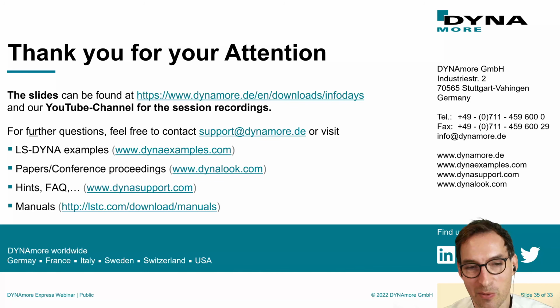Okay, just as a follow-up question, last one. I think this applies to ALE and SPH, right? The question is, does it work with all material models? No. With ALE, you have this advection step all the time, and advection requires a special treatment also in the material. A lot of materials are implemented, the usual suspects, I would say. Give it a try. LS-DYNA will tell you, hopefully, that this material is not supported. Run a really simple example with the material you want to use in ALE, and see if LS-DYNA complains or not.